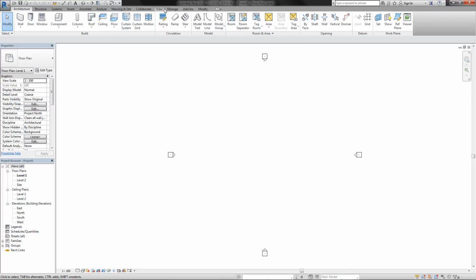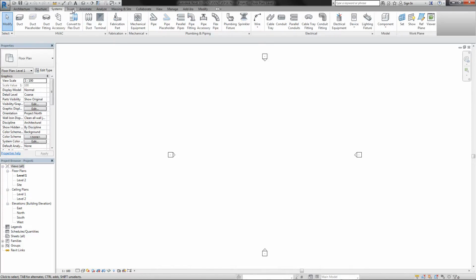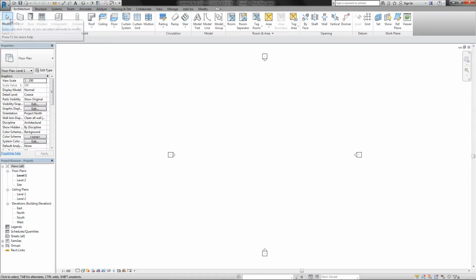And then we have this ribbon and tab, where you can go through different categories of things that you can do in Revit. And then here in the ribbon, you can see different options and different functions you have. There on this side, you have properties, and you have your project browser. So in your properties, as it says, you will see the properties of the object you're going to draw or you have selected. And then on top here, you can select different types and families. We're going to talk about what is family, what is type in Revit in a bit. And then down here, you have your project browser, where you can see different floor plans, sections, elevations, your sheets, your legends, your schedules, and everything you might have in your file.